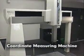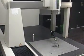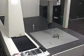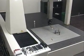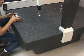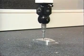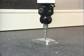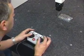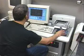The coordinate measuring machine, or CMM, is an extremely accurate measurement instrument that provides detailed data and documentation of manufactured parts. A typical CMM system consists of 4 elements: a machine frame, usually constructed from a granite or other thermally stable material for securing and supporting the part; a probing system used to collect raw part data; machine controls, when machine motion is motor controlled; and a computer system and software to process and analyze the raw part data.